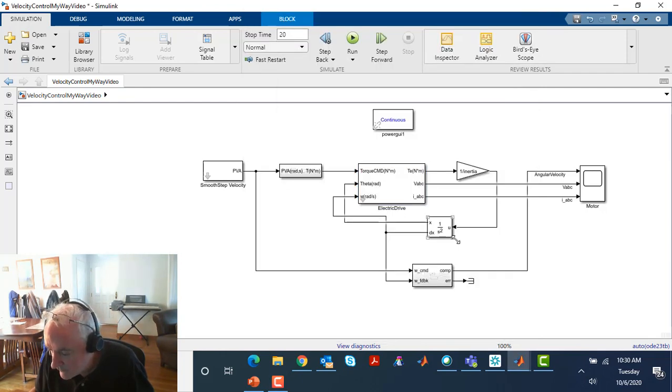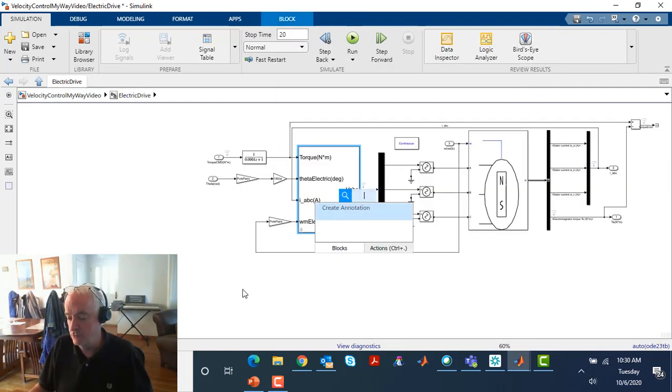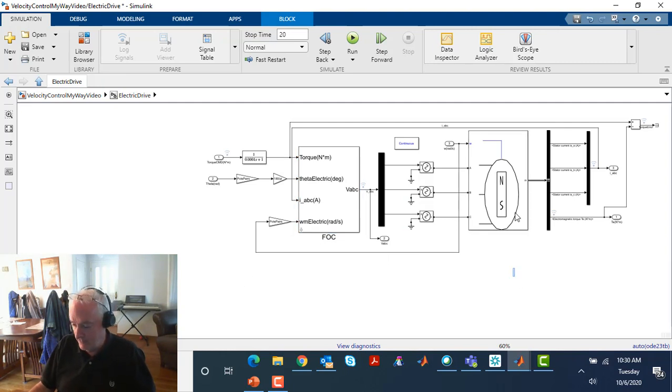All right. So I want to jump into this thing we call the electric drive a little bit. We'll see there's our permanent magnet AC motor with its 3 electrical connections, and here essentially is our algorithm. Our algorithm's job is to deliver the voltages that will be put on the A, the B, and the C terminals. The way the algorithm works is mostly commanded by what we want to happen, as expressed by the torque.